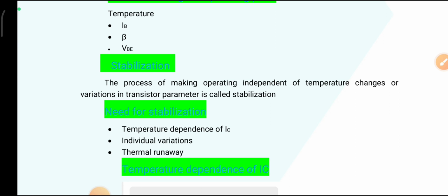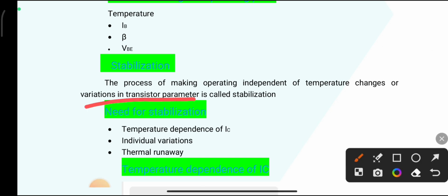The operating point must stay constant, at some point in the middle of the active region, irrespective of temperature changes or variation of transistor parameters.